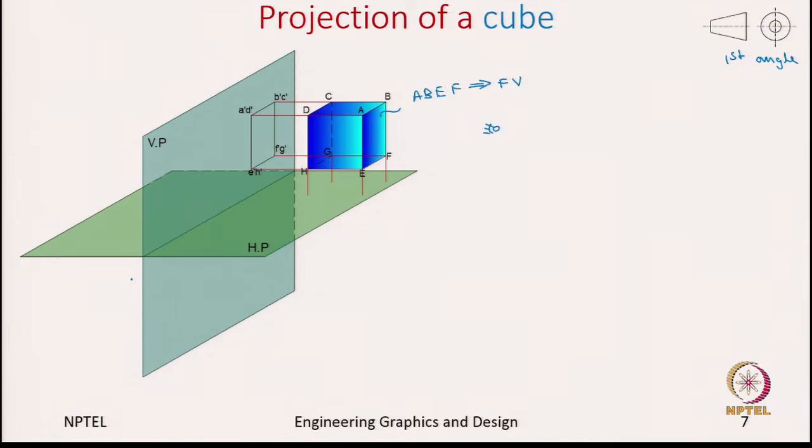Okay. Now, once we are capturing the top view, which means the observer is looking from the top, what he first notices is this top face, which is A, B, C, D. This is the surface he is looking at, but since the projector lines continue from A and then pass through point E, one needs to mention both these points, and the sequence will be first A and then E. So, you notice how we are mentioning these points A, E, D, H, because the projector line first passes through D and then to H before it projects onto the projection plane.